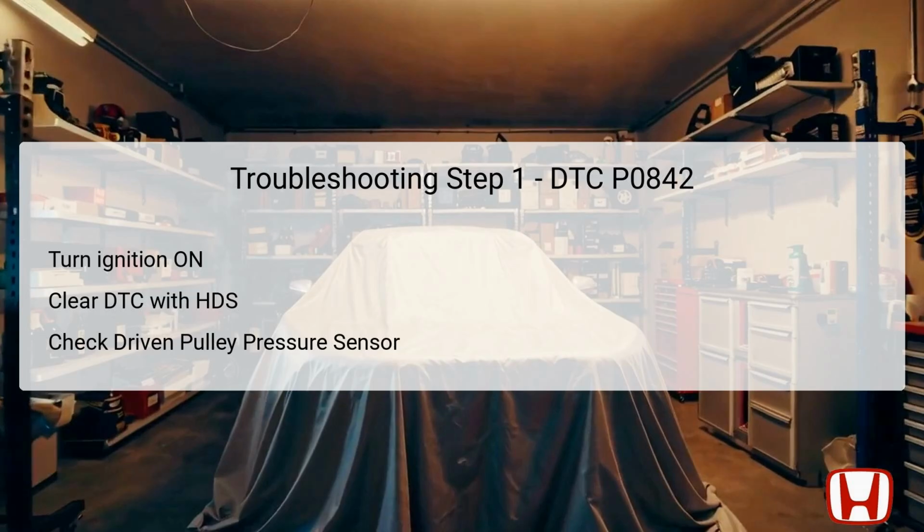Following this, check the driven pulley pressure sensor voltage using the HDS. It should indicate 0.21 volts or less. If the reading is at or below this threshold, it confirms the failure is reoccurring, prompting you to proceed to the next troubleshooting step. If the voltage reading is above this level, it suggests an intermittent failure, and you should try to recreate the conditions leading to the fault, if freeze data or onboard snapshots are available.